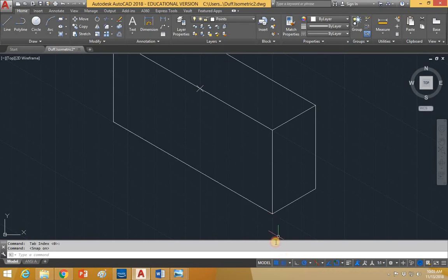All right, so let's turn our grid snapping back on so that we snap onto the grid. We'll come back here, we'll hit PO. We're going to come up 3, 2, 3, and now O-snap's on, so it's wanting to send me someplace weird, so we'll turn O-snap back off. 1, 2, 3. So now I have a point at 6 and a point at 3. So I can go through, grab my line, click, click. I know it's got to go this way at a 30-degree angle.